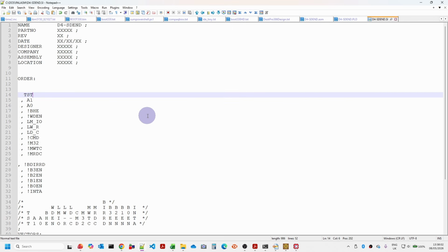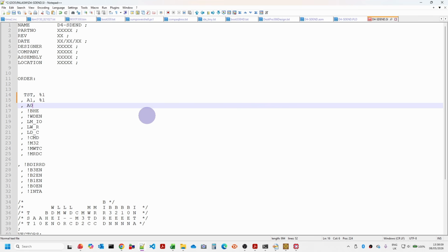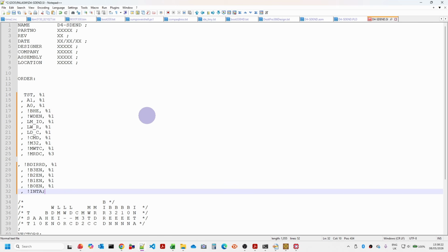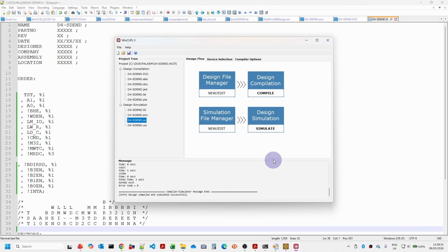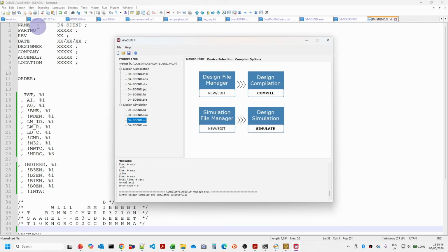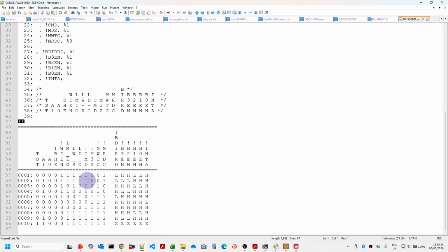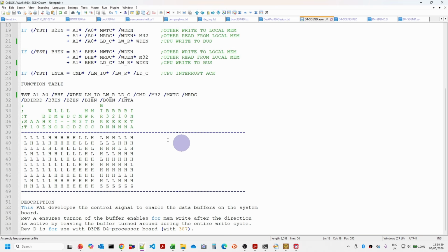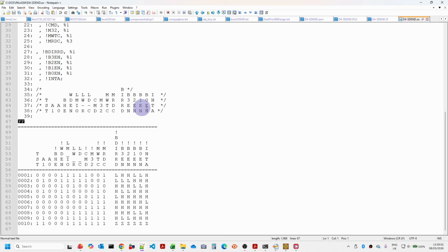And what we can do is if we go back into our simulation file, put a comma %1, and we do this for every column, we'll just add spaces. An extra 2 spaces there. And in fact, there is a semicolon there. The semicolon is actually down below the comment there, but it's generally easier to put it there. So now if we rerun the simulation, we now should have a slightly nicer output. Now we look at the output there, you can see this has actually produced a much better output. And in fact, if we open this in here, we can see if we compare this to the SI file and also to the ASM file, it makes it a lot easier to actually compare these things.